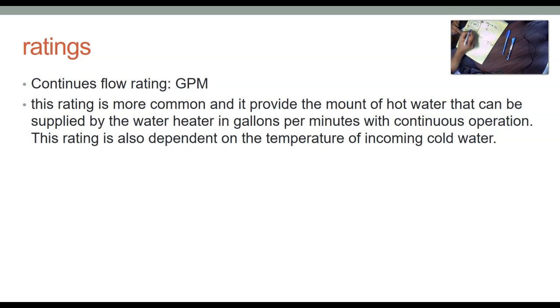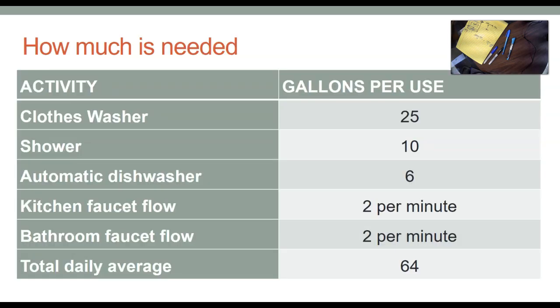However, at the same time, you are heating this water using electricity, gas, or whatever. So how much heat you put in and how much water is coming in matters. There's a big calculation to tell you how much constant hot water you can get going forward. And the efficiency of the heater versus the cold water coming in determines how much you can get from that boiler. I hope this makes sense, but it's good to think about it this way. And where you install the boiler makes a difference, because again, we are counting a lot on the incoming water.